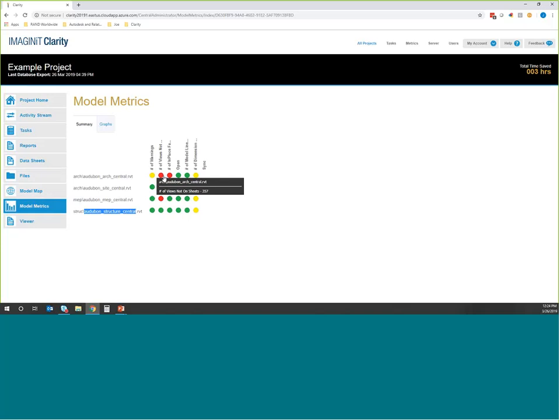That seems maybe a little excessive because I'll tell you right now it's a small Revit file. It's like 30, 40 megs, 45 megs maybe, small. There are 70 in-place families on that small Revit file. That's probably an opportunity for a lunch and learn topic for the firm, so that we can understand why it's maybe not good to create an in-place family and copy it 70 times through a building, and give us that learning opportunity.